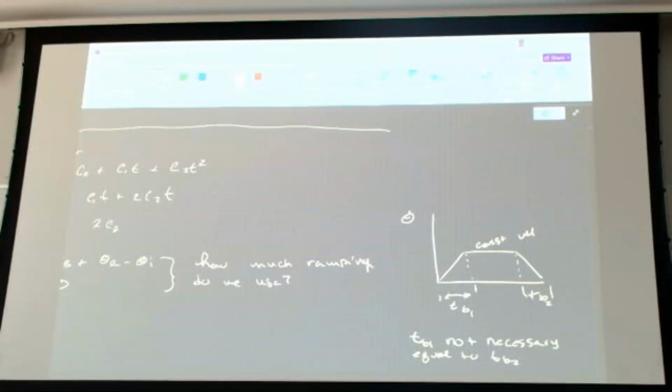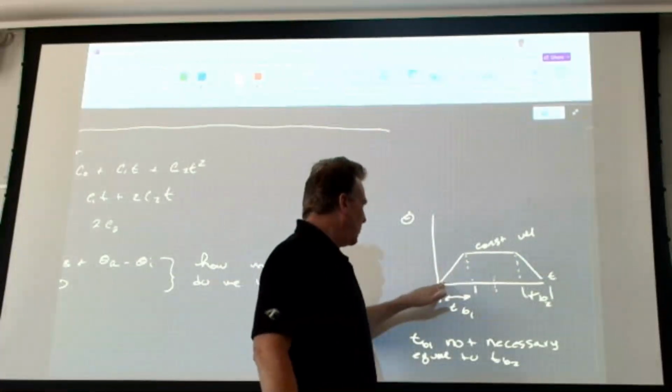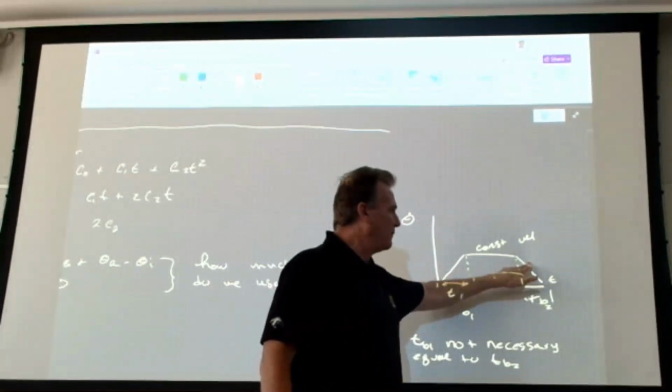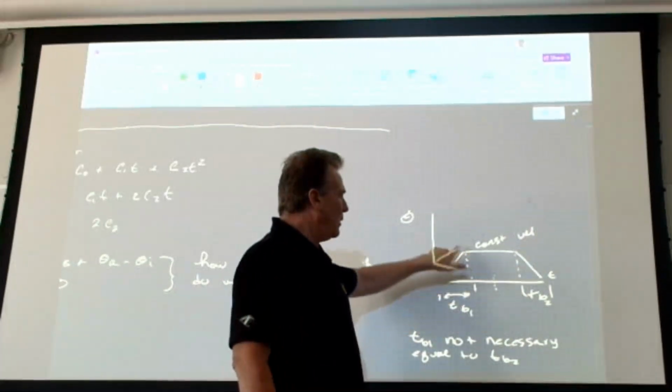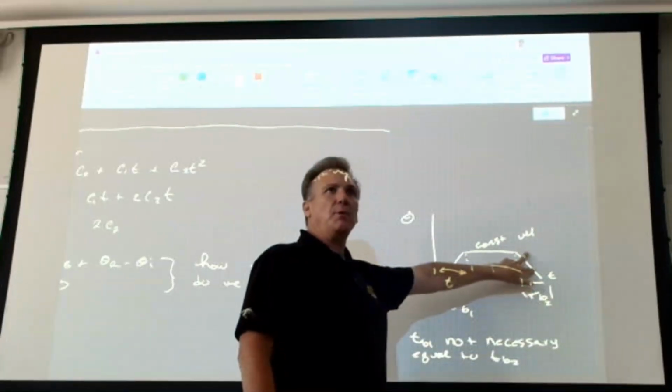That means they can be an asymmetrical motion profile. Most of the time it's not, but it does have to. So in other words, TB right here, we can't, if TB is beyond half of T, right, I got my final T right here, I haven't finished ramping. So in other words, if I set my ramp time to be here, I'm ramping here, I may not have enough, in fact, I may never even finish, I may never get to a constant velocity. So we have to make sure that all of this is doable.